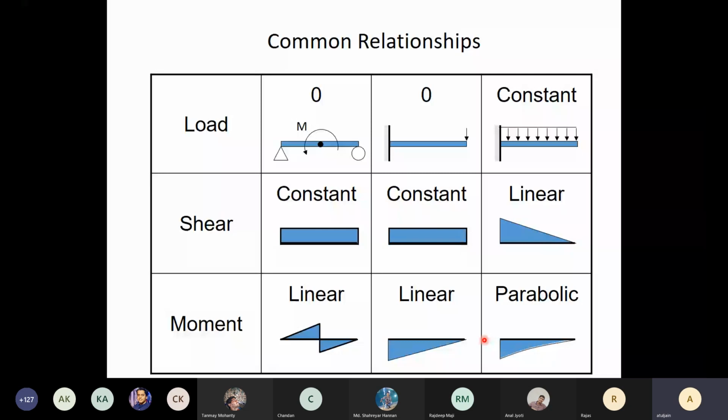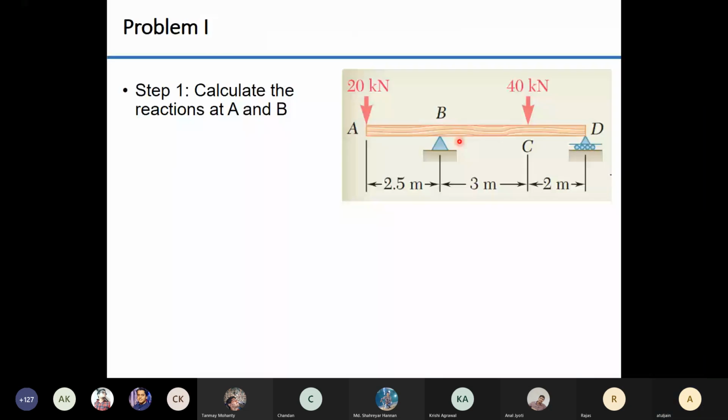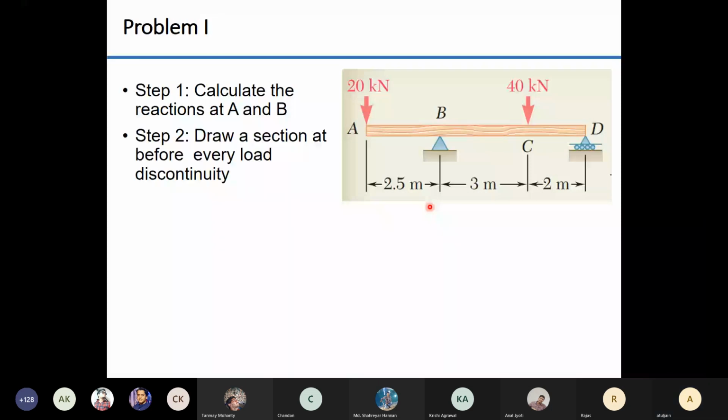The principle of superposition holds true, meaning to say that if I have a problem like this where it is subjected to 2 point loads, I could actually do the bending moment diagram all at once, or I could draw 2 separate bending moment diagrams for 1 point load each and add it up. Both are okay. So if you know how to calculate the bending moment diagram for point load, distributed load, and moment, then whatever problem we have to give you has to be a linear combination of all three. And the principle of superposition is true. So make sure to understand how to calculate it for these three cases, and then you are done.